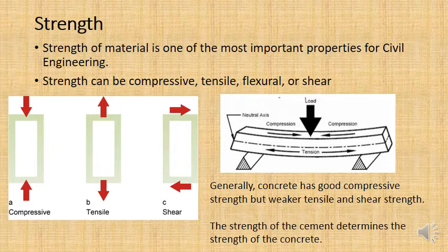So if you were going to have a concrete beam and you were going to apply a flexural load, where would the beam crack? Would it crack on top of the beam, or would it crack at the bottom? Well, it would crack at the bottom first, wouldn't it? Because that's the part which is in tension, and the concrete is weakest in tension.